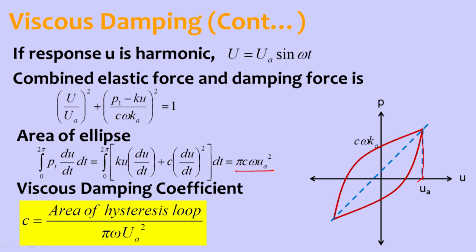Now, in summary on the types of damping. In all structural engineering applications, damping is usually under critical damping. Critical damping is the damping value required to completely remove the energy of vibration. If damping is less than critical damping, it is called under-critical damping. If damping is more than critical damping, it is called over-critical damping.